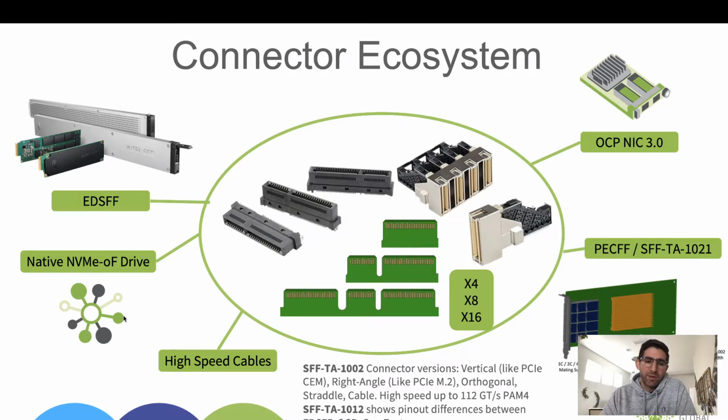Now there is an SFF-TA-1012 that shows the pinout for other types of devices as well, including a native NVMe over Fabrics drive or an Ethernet SSD. They'll be using the same connector. The connector itself is also capable of high-speed cables. So there've been some really cool, unique designs where maybe you could cable out from the CPU over a high-speed cable directly to a slot, where you can have really low-cost attach for PCIe Gen 5 and beyond.